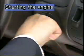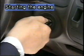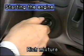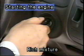Now let's look at different driving conditions, beginning from when the vehicle is started. Naturally, the engine is cold, making it harder for the fuel to be atomized. This alone is enough to create an improper air-fuel mixture. Hence, it is necessary to provide a greater ratio of fuel to air.